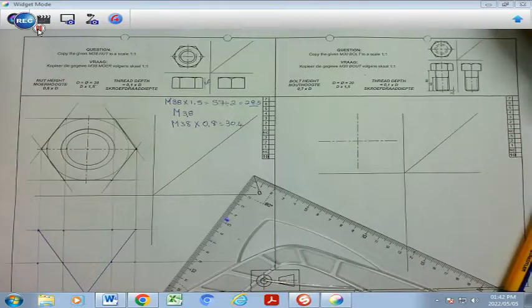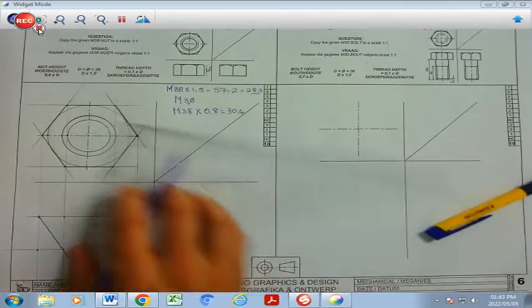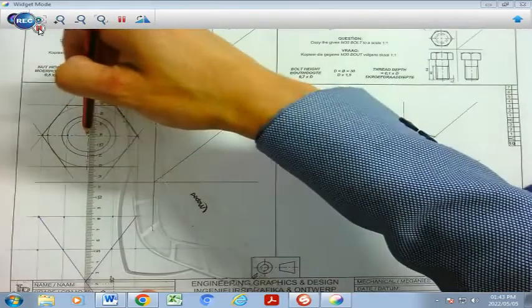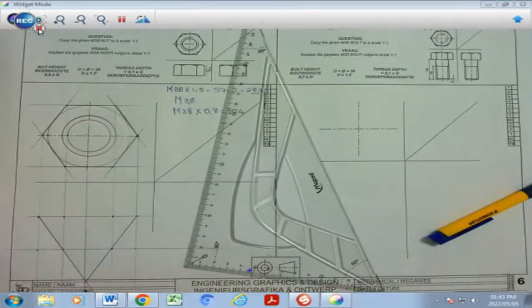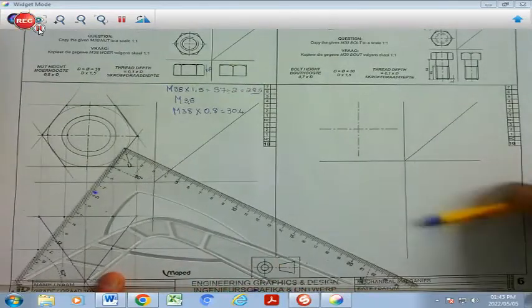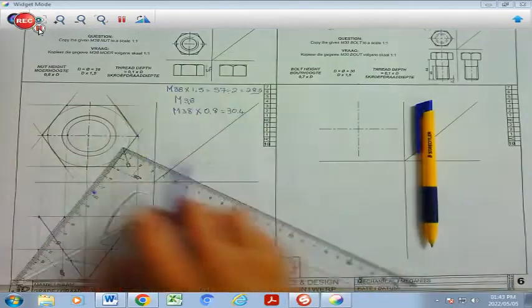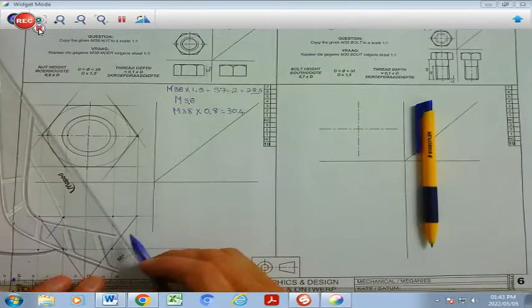You are going to find significantly that my point actually meets perfectly in the center. If I am going to project that center point down, it will exactly meet up with the center line, with the 2 lines crossing here. I'm going to project 60-degree lines from the inside top corners as well of my 2 faces.